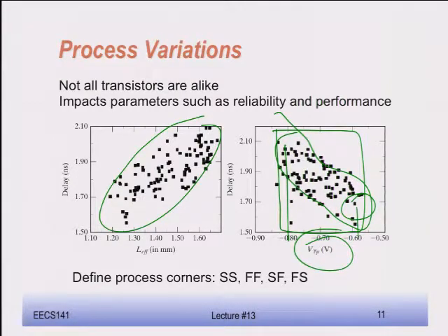So I just wanted to point out that process variation, you shouldn't be thinking that I'm simulating my thing, I get a number out there which says my propagation delay is going to be 1.27 picoseconds or nanoseconds, and you simulate it and you have 4 decimals. When you get your chip back and you measure it, you're going to be all over the map. So never give me results of propagation delay simulations with 4 or 5 decimals. It's meaningless. If I get 1.2 nanoseconds, I'm already going to be quite happy. That's more than accurate enough. Okay? All right. Good. So that's the DC characteristics.